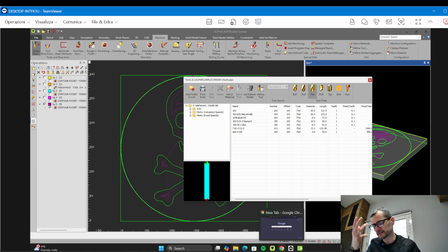Yes, so, and it's not right that I answer because I don't know. If I'm in front of the machine, I have, for example, a 3mm diameter, I say, okay, I try with a really low depth, and you see what is the time before it breaks, and it will break for sure. So also a connection with the seller of the tools can be interesting to have. So you need to practice with the machine, in my opinion.